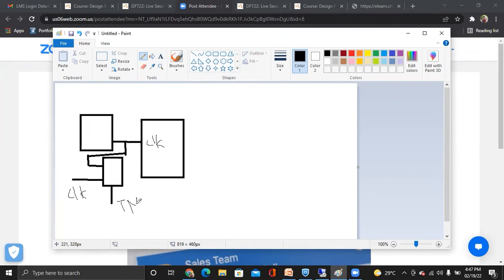Someone asked where we are using test mode. So what is the active state we have given? This is 1. So the select line, if it is selecting 1, so if test mode is always 1, then it will always take this clock only. It will continuously select this clock. So now, instead of taking the clock from another clock, you are taking the clock from the top level port. So doing this will resolve the violation.